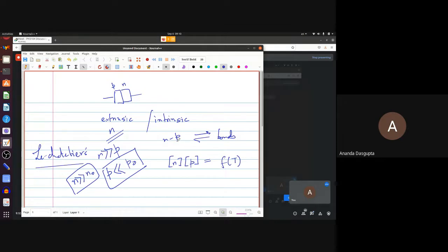So what you do is you create a bunch of diodes. You don't really make one diode. You create a huge number of diodes by the same procedure. Take away a random sample from that. Carry out these characterizations, including checking when they burn out on that sample. Take the average value for that, and then if you find that in your sample diodes are typically burning out at a mean value of around 4 amperes, then you quote the safe value as around 1 ampere. So if you ask what will happen if you just exceeded the safe current, your diode may still survive. But it's better not to try that.